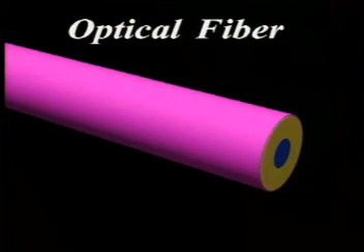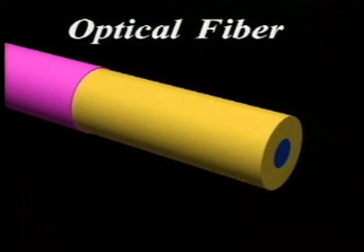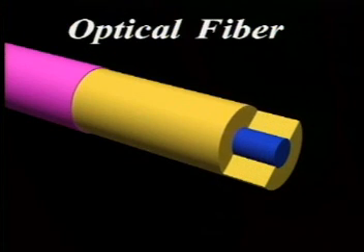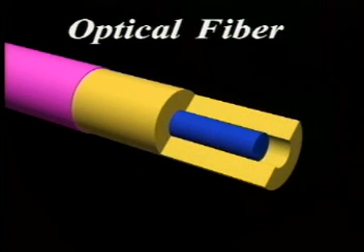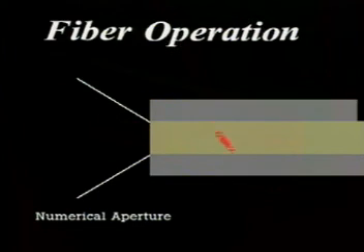An optical fiber is made up of three parts. The first is the buffer coating. Made from plastic materials, the coating provides protection against bending and mechanical stress. Under the buffer coating is a layer of cladding, usually made of pure silica glass. The innermost part, the core, is also made of silica, but is doped with certain elements to provide a refractive index usually higher than the cladding. The difference in refractive indices between cladding and core forces light to be totally internally reflected along the fiber waveguide.